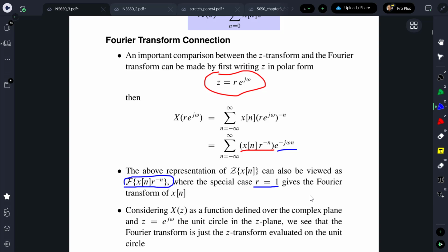So this supposedly is hard to visualize in the beginning. When I was first teaching this subject, my mentor, Dr. Ziemer, who was the department chair when I came to the faculty, but he was my dissertation advisor back at Missouri S&T, he said, students won't get that. The Z-transform evaluated around the unit circle is the Fourier transform. But I said, they know this from the S domain and the Laplace domain. If you have the S plane and you go vertically on the j omega axis, that's the Fourier transform. If you sample on there, it works almost all the time, but not all the time. So I'll be talking about that here too.